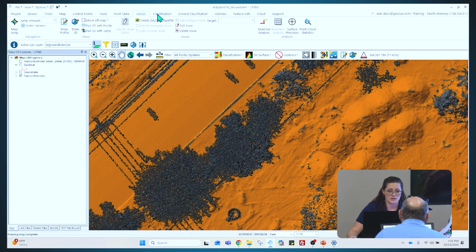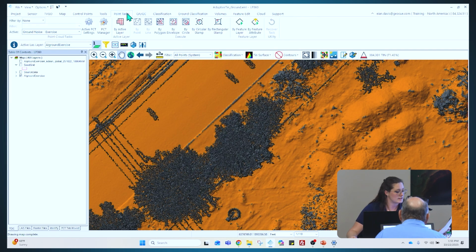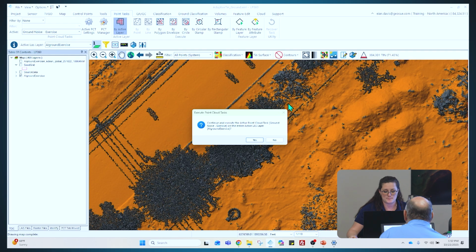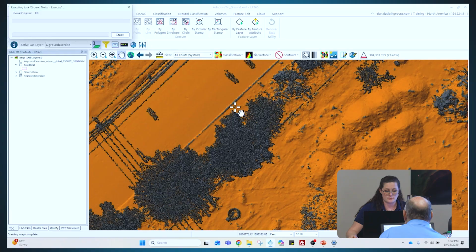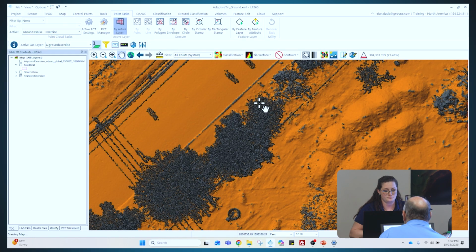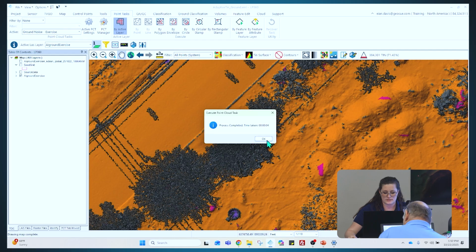Okay. Now that we've done that, we are going to execute this tool, and I'm going to do it by the active layer because I want to review the statistical noise of my entire point cloud. All right. So I'm going to click yes here. I'm going to let this run. All right.